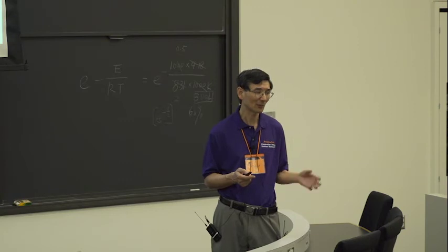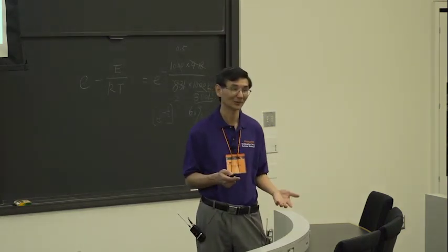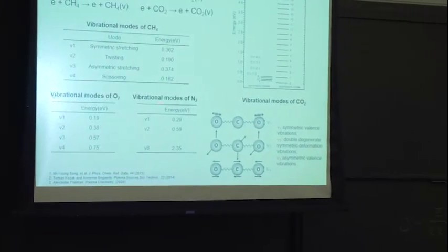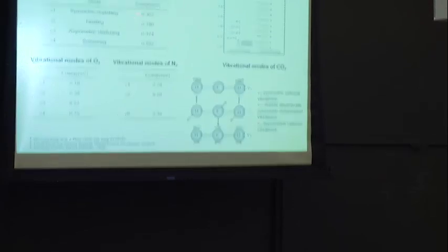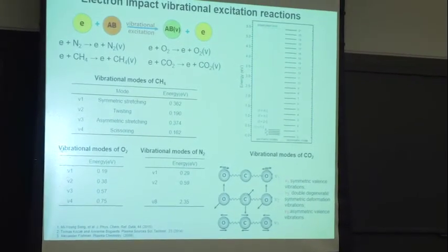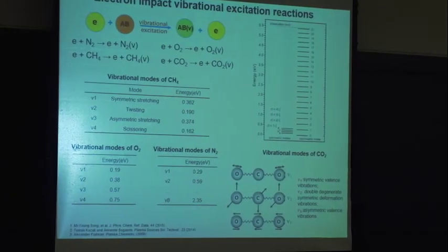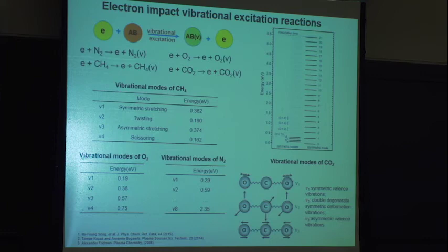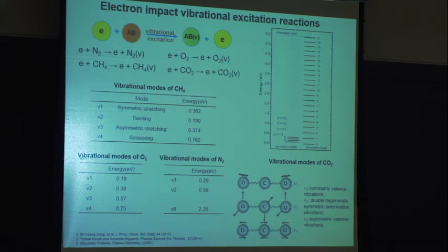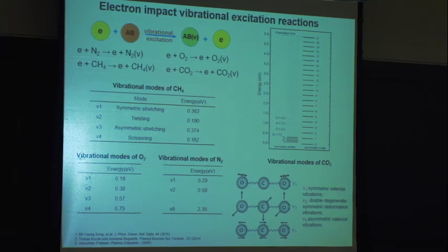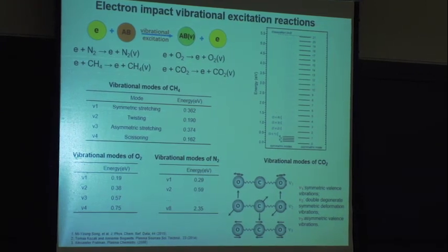So what is the plasma process? If a plasma just generates radicals, it's not a good reforming process. You want the plasma to generate, for example, vibrational methane, with very low energy. What is the energy for vibrational methane? Here you see it is 0.4 or 0.2 electron volts. So that vibrational methane probably sticks to the catalyst. Probably you directly need to dissociate, and then go into hydrogen formation, right? So the question is how much vibrational methane is generated? How do you quantitatively measure it? Right? Vibrational methane. That's the key question to be answered.